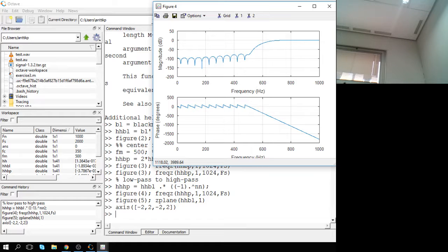Just one warning: when you are adding these filters, you are also adding these stop band properties, so you are pushing the stop band attenuation a little bit less. So you can expect to read 3 dB less attenuation on the stop band, but usually that's not a big deal.